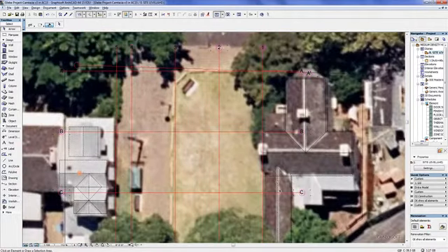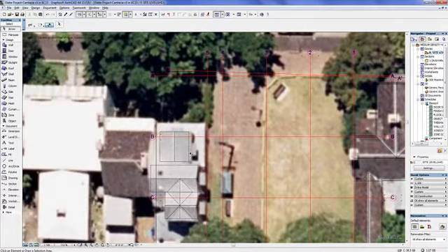And then what we need to do is determine now the relative level of this and the relative level of this. Okay, similar to what we did over here when we were determining the relative level of this pair of roofs as opposed to this multi-plane roof. And what we did here, remember, we lowered this down and then we fixed this end part with the scissors click method. So that's what we're going to have to do here.